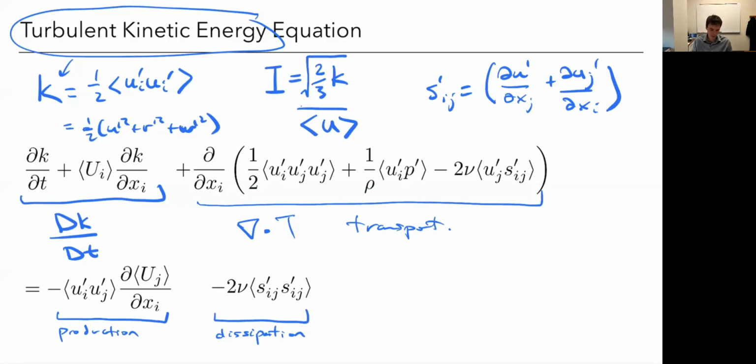For one, to introduce K, which is really important, right? That's the key concept. This is the kinetic energy associated with the fluctuation. So it tells me how much energy is in the turbulence, whether it's very turbulent or not very turbulent, or we can express it in turbulence intensity. But this equation also tells me something about the physical mechanisms of turbulence. We call this an energy cascade.